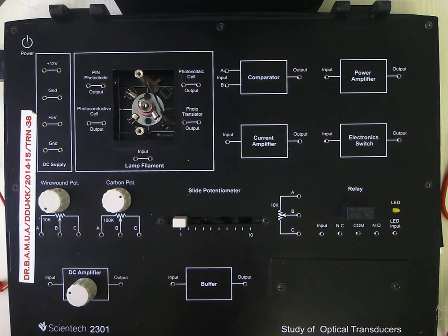You could have easily followed the output of the sensor is having only two states. Either it is giving a high signal at the output or it is giving a low signal at the output. Normally such sensors have got three wires. One is connected to the supply, other to the ground, and the third pin that gives you the signal.